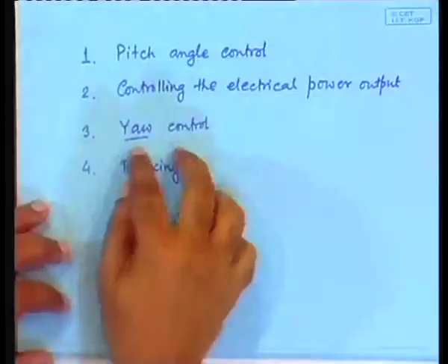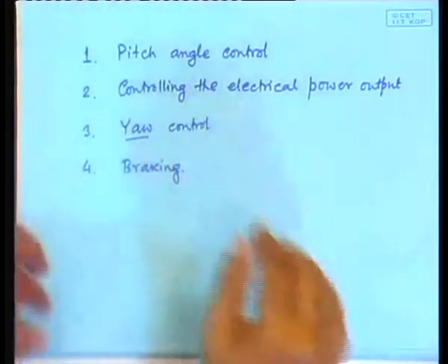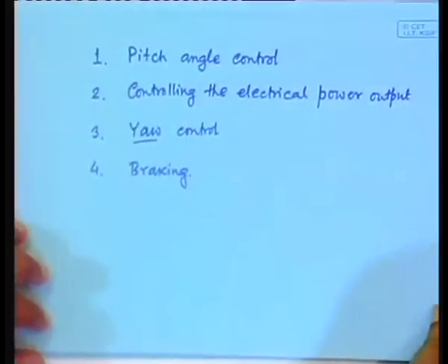Moreover, if you use yawing as a control mechanism, you will have to move it all the time, and turning this huge structure sitting on top of a tower is not an easy job. It requires power. Not only that, it also makes sound. You can hear that sound, yawing. So, it becomes somewhat undesirable to do that. But nevertheless, you should know that it is a control mechanism in your hand.